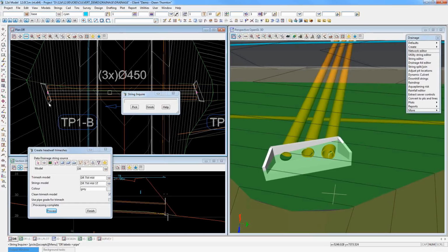Obviously the head wall needs to be a different shape as well. It gets quite complicated, skew head walls and skew culverts, and I don't think they tend to like making them much anymore, not as much as they did in the past. Certainly they much prefer non-skewed culverts and non-skewed head walls because it suddenly becomes a much more complicated problem. So yes, the wing wall angles and all of that, you need different head walls for that as well. So in answer to your question, you can go some of the way, but perhaps not all of the way with the tools that I've shown you in this webinar.